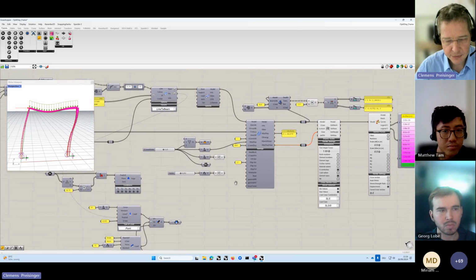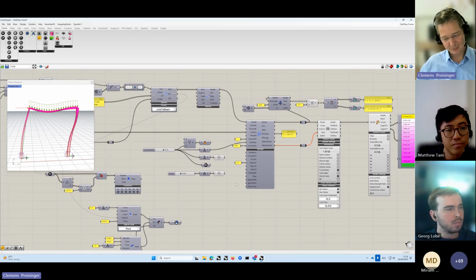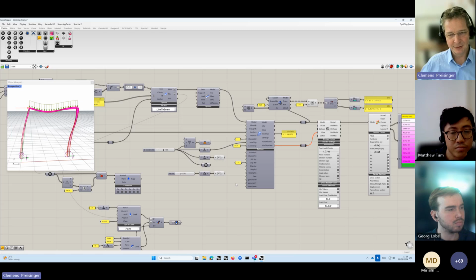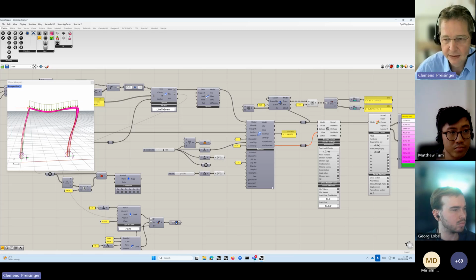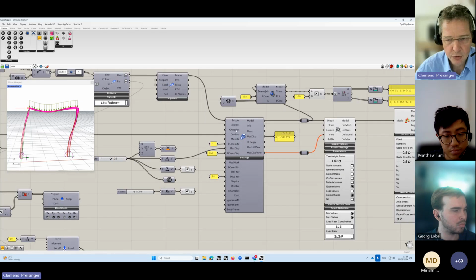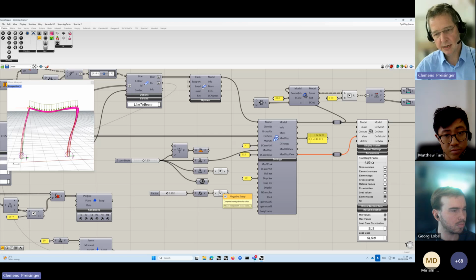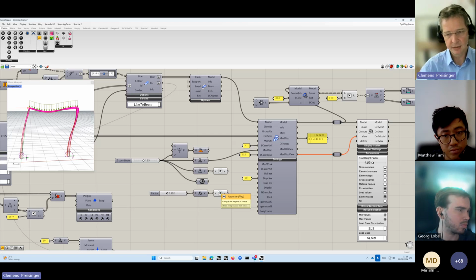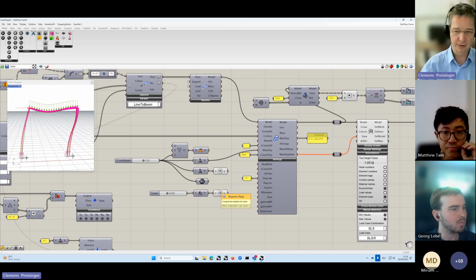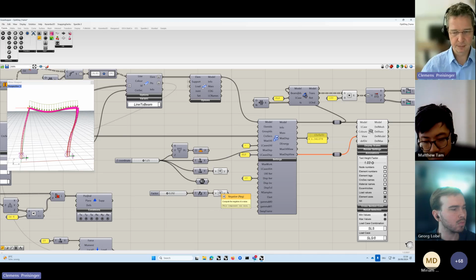And of course, to make this more useful, it was also important to update the cross-section optimizer to make full use of these load case combinations, because the main point of application is to be able to differentiate between the serviceability limit state and the ultimate limit state, because different safety factors apply depending on whether you optimize towards maximum displacement or collapse of the structure, of course.